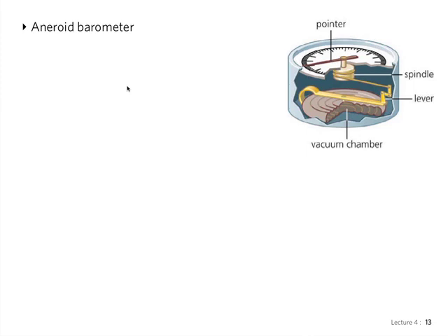They've sucked out all the air from it, so it's at a vacuum inside, pretty close anyway. This elastic element will deform in response to outside pressures, and that motion is read by a mechanical lever which turns a needle. Simple as that.